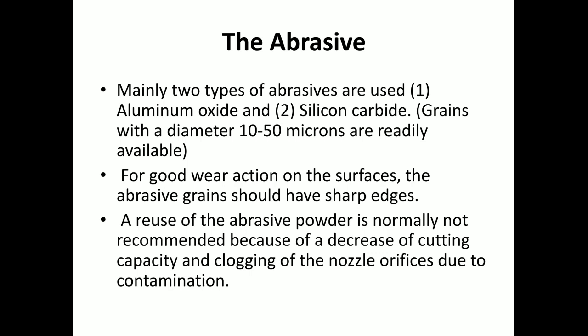Clogging of the nozzle orifice due to contamination also occurs because when these grains impinge on the workpiece, dislodged material also comes with the abrasive particles, and when they mix they create clogging in the nozzle. So it is not recommended to use abrasive that has been used once.